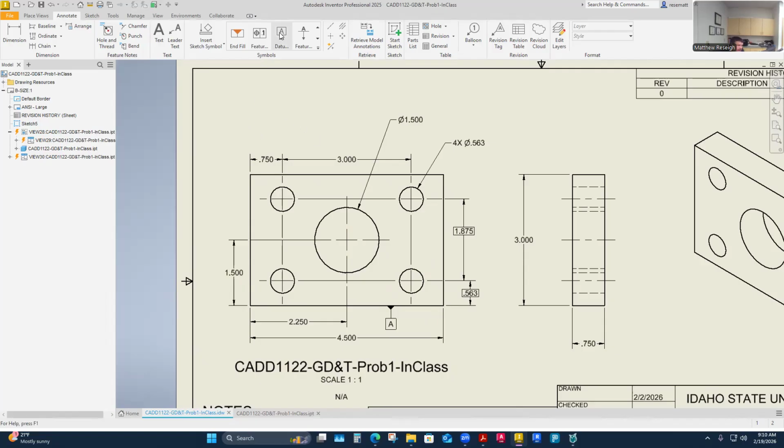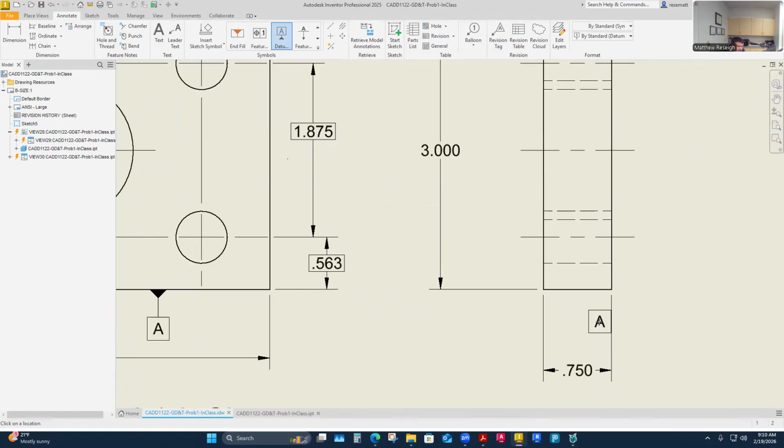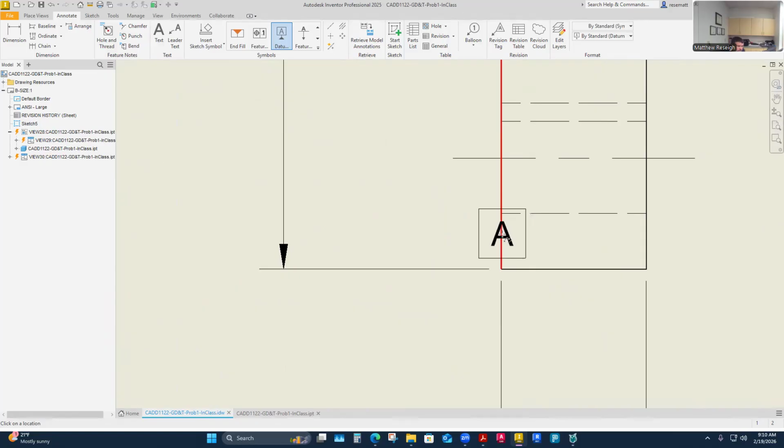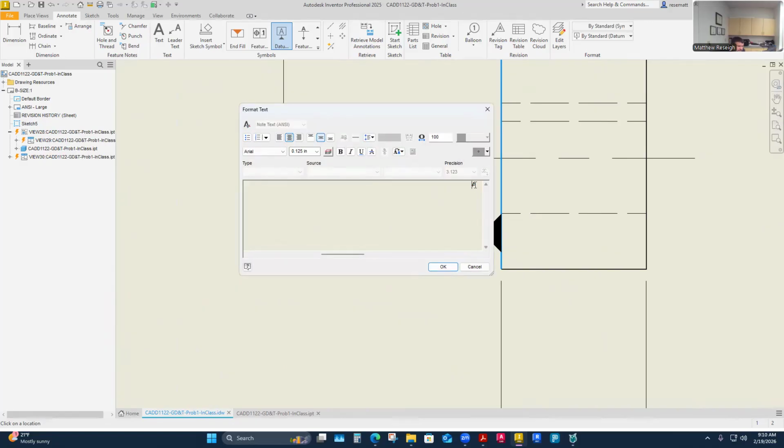And so you have some options, right? I could actually do one here with a dot on a leader line. That would be that surface. Maybe this is the most clear. And for my GD&T 101, I might just say this is the surface that's datum B. So I'll go ahead and drop this one. I just need to change my datum to B, capital B. Someday I'll write it here. B, yes.